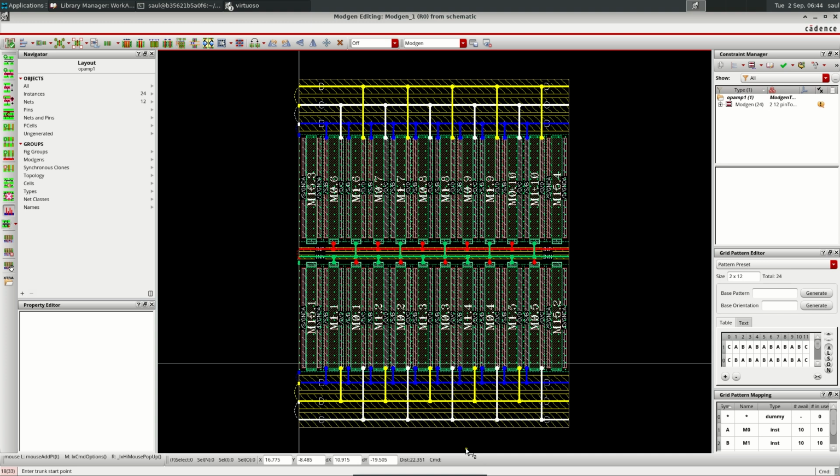So what did I do here? I added the D and C nodes connected, but I want both sides to have the same parasitics, so I put one close to B and one close to D here, so that they both have the same parasitics.